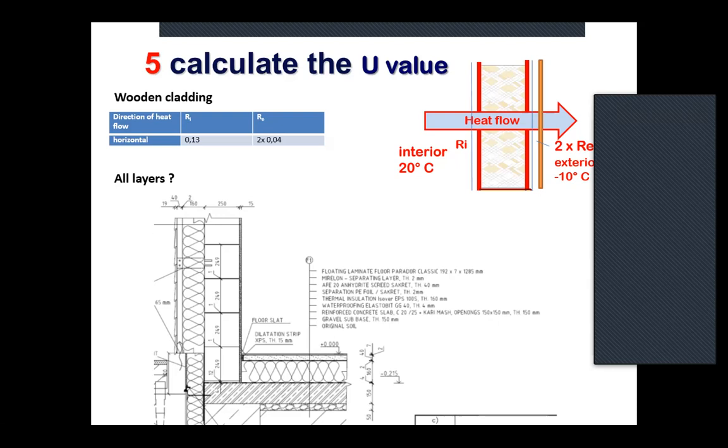So the general advice is to calculate only up to our waterproofing layer, our damp proof course, to the point which is still safely dry.